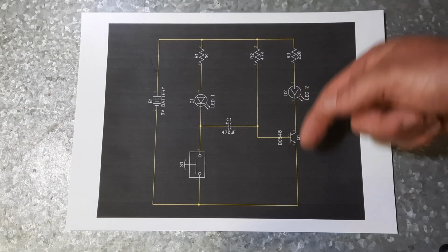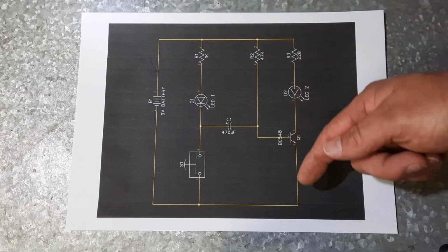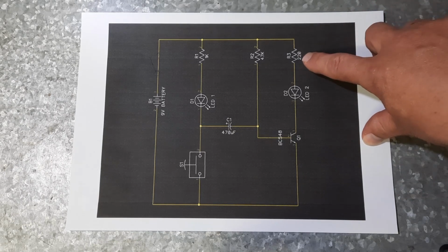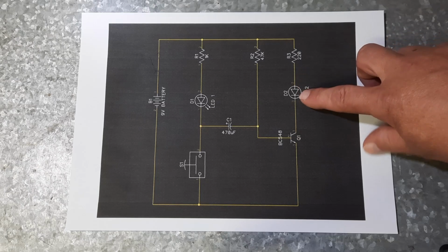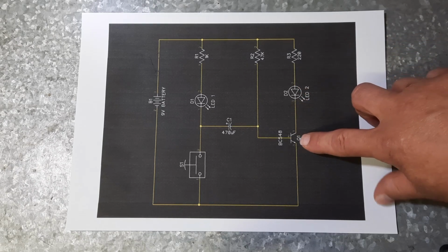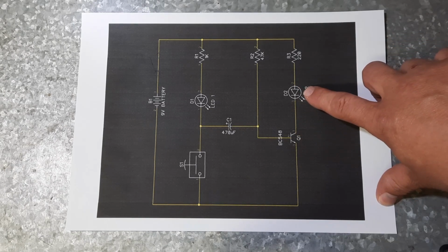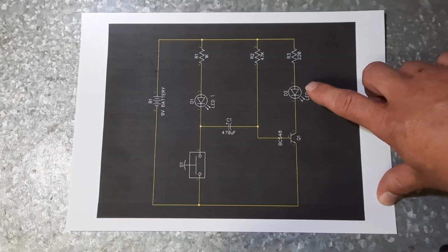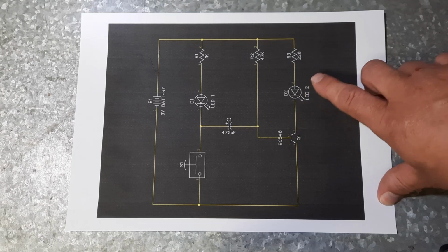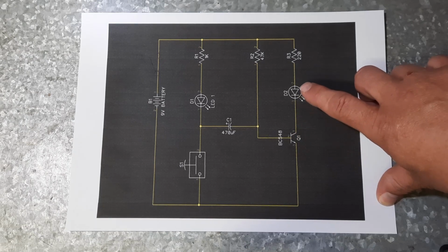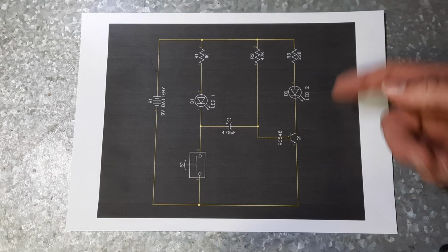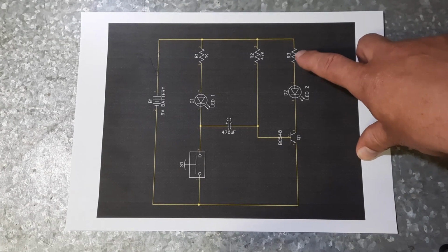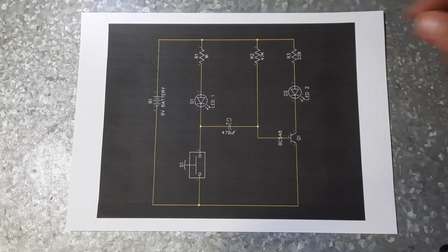This LED is going to have current flowing through it. It's going to glow. So it's going to light up. This resistor here is here to limit the current through the LED and the transistor. Both the LED and the transistor have a maximum current rating, which if exceeded will damage both of them at the same time. As soon as power is applied to it, if you exceed the current rating of either of them, you'll destroy them. So that's what R3 in this circuit is doing. That's its purpose.